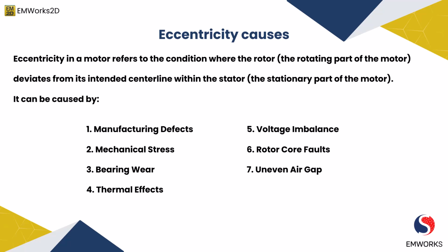Second, we have mechanical stress. External mechanical forces or excessive mechanical stress on the motor, such as impacts, vibrations, or improper handling during installation, can cause the rotor to shift from its intended center line, hence resulting in eccentricity.